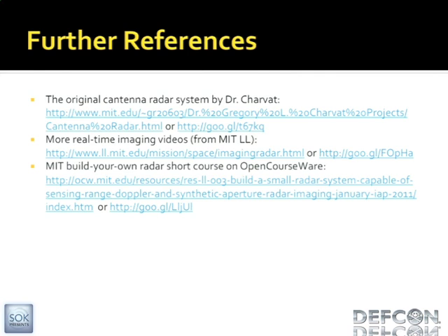The frequency bands that you can operate in, there's a few bands you can operate in. You pretty much are stuck to the ISM bands if you want to do this stuff legitimately, because those are what's licensed for this unrestricted or pseudo-unrestricted use. So you could go up to 5 gigahertz. It would be a little harder to find parts. Basically, as you go up in frequency, the parts just get a little more expensive, or as you get even higher, they can get a lot more expensive. But the big thing you want in a system like this is wide bandwidth, because the bandwidth is what's giving you that spatial resolution and the time resolution.